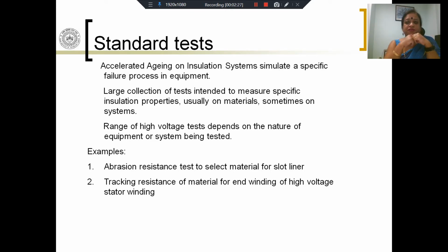The coefficient of thermal expansion of the conductor material will generally be larger than the coefficient of expansion of the surrounding insulating material, the lining material. So as a result, there are shear forces due to unequal material expansion due to loading, due to high current.